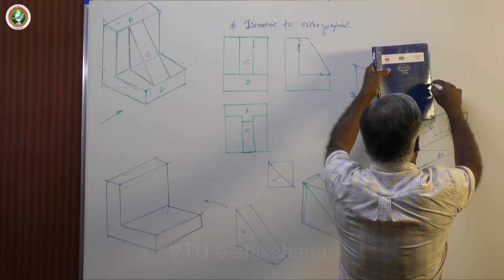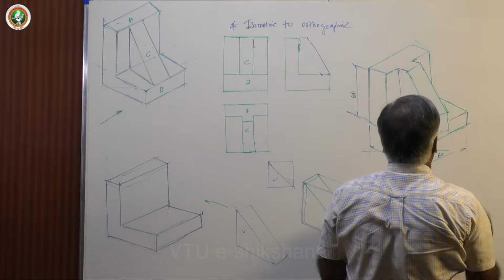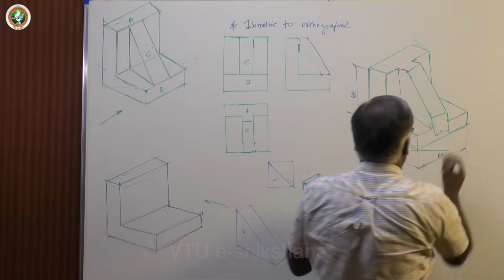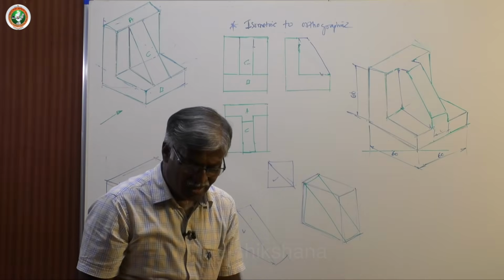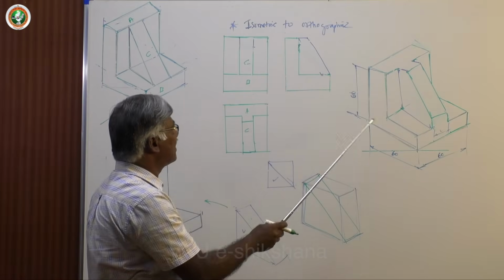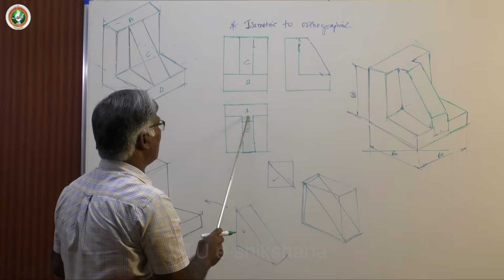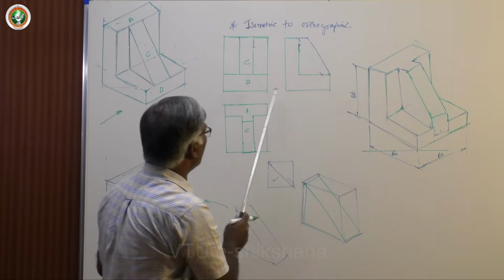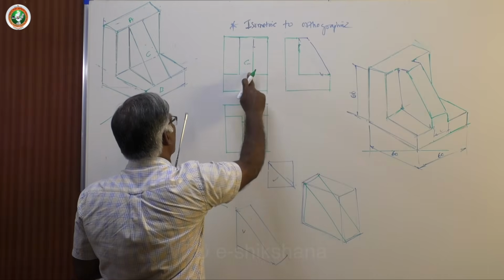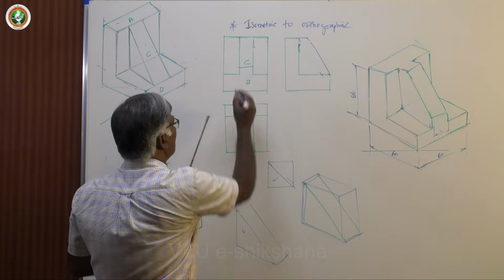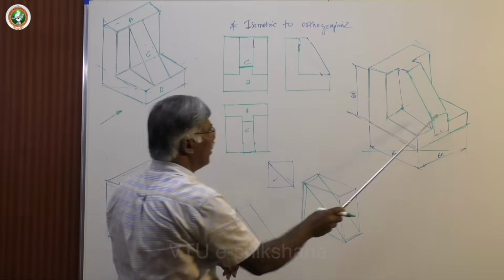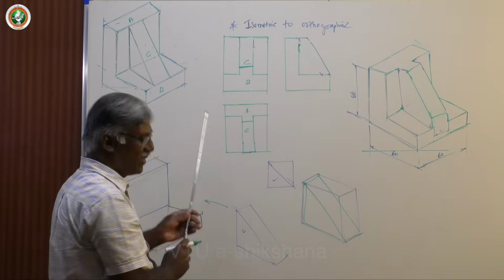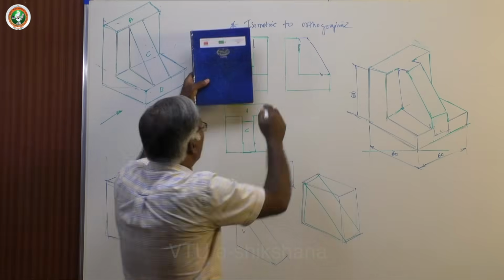And visibility of these lines depends. Okay. Now, as we did in the previous case, this contour is available here in top view. You can see the contour in top view. Fine. What about front view now? Same type of contour is available in front view also with 10 mm up. Okay. Then it will continue up to the top face. Irrespective of the contour, same line will work for that. Now, front and top views are over.